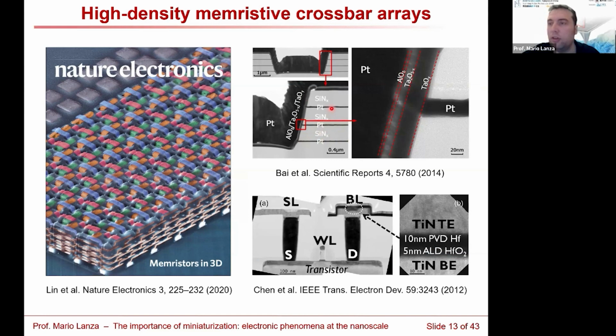Here are the platinum bottom electrodes, and then we put the insulator along the edge of one cavity that has been patterned in the wafer, and then this part here will be the top electrode. So we have one memristor laterally in this way, another memristor laterally in this way, so you can see a better picture here. So this is also very interesting.